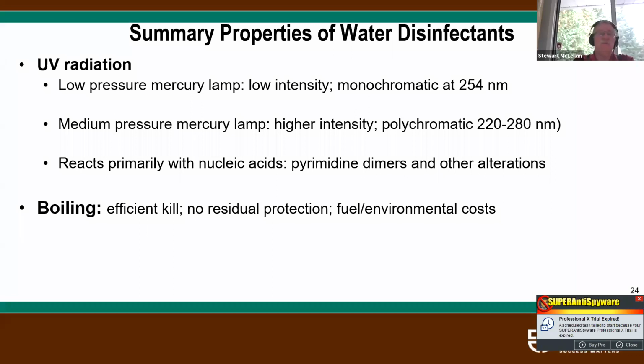UV systems are very common with small scale groundwater source potable water supply systems. Many people will put a UV system directly in their home immediately after the supply point of the water, so that the water has to pass through the mercury lamp prior to being used within the house.